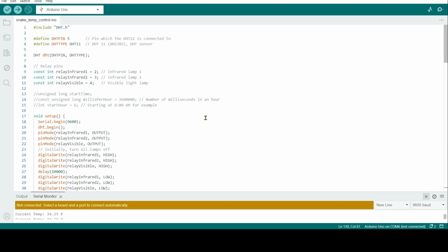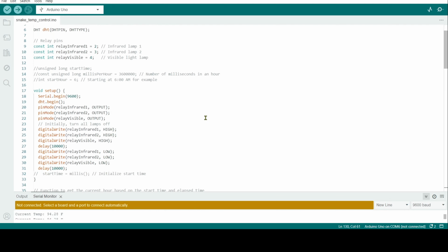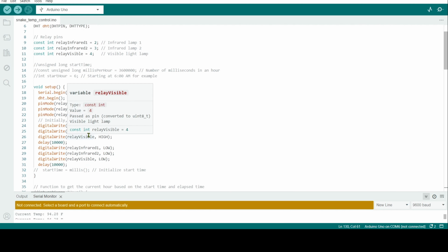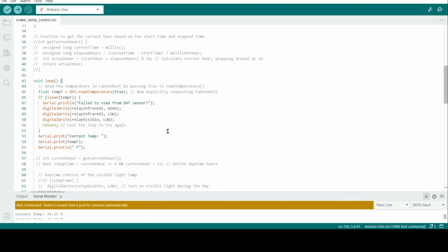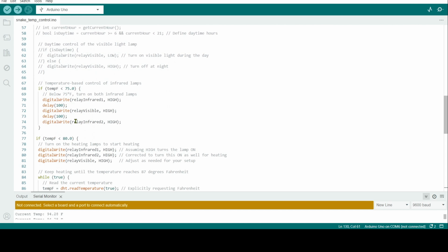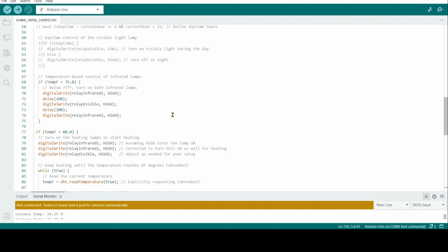And it's obviously not a code issue. And the relay works when I'm powering it up. When I did the power up and we turn them all on immediately, it was functioning. But then when we got down here in this loop, this relay, infrared relay 2, just kept on, off, on, off. It was interesting and concerning because if I'm not home, I don't want a relay switching continuously until I get there. Potentially have some mechanical failure or electrical failure of the relay.